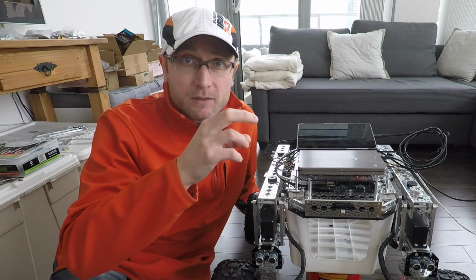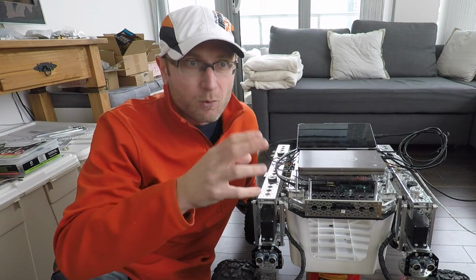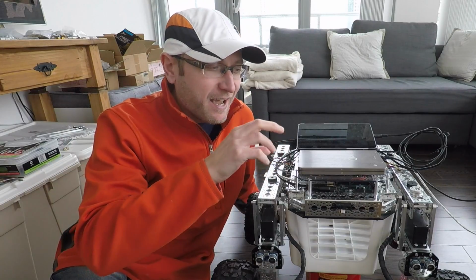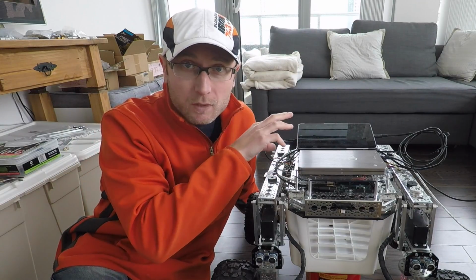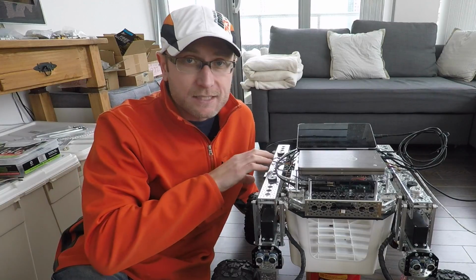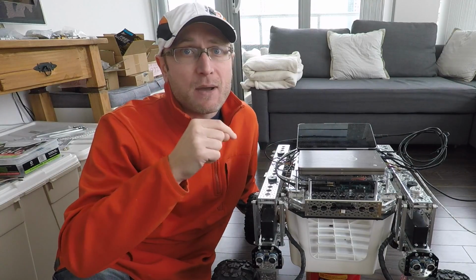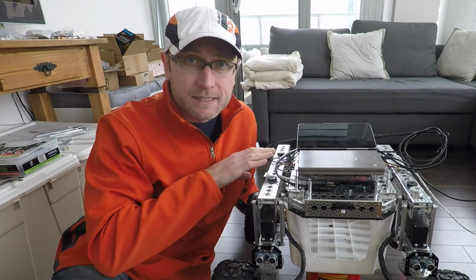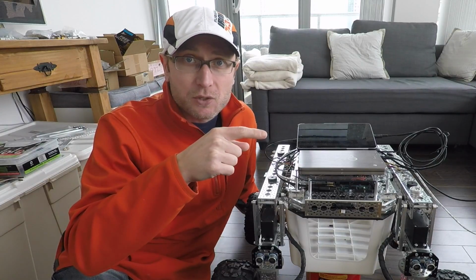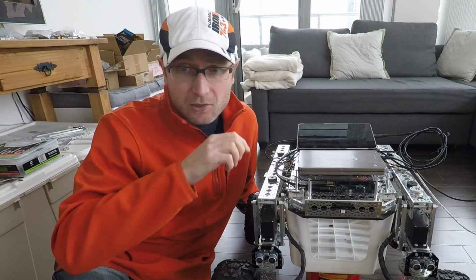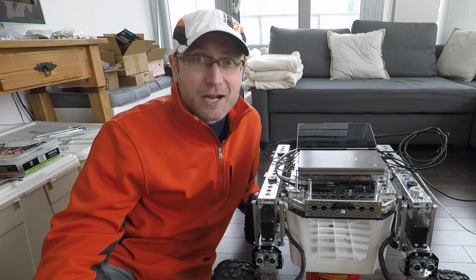In the last episode, we looked at debugging rover's crash, and there were two main culprits. There were a few more, but there were two main ones. One was the buffering in the RoboClaw motor controllers, and the other was the sensor anomalies. I had the buffering issue addressed, and I think I now have a solution for the anomalies in the sensors. Let me show you that before we get rover started down another autonomous test drive.